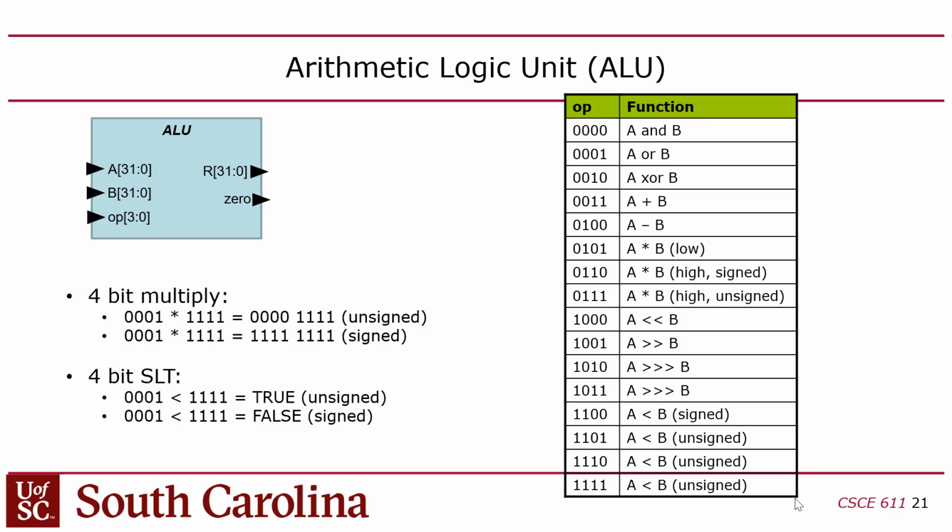Yes? So you connect up the output of the reads from the register file to these A and B, and then the output of the ALU to the write data? Yeah, basically, you got it. So you don't need a mux anymore because we're not going to store? Well, you do need some muxes, but that's a good point. Is there a mux going into the write on the ALU? Yes, there is. There's still going to be a mux.